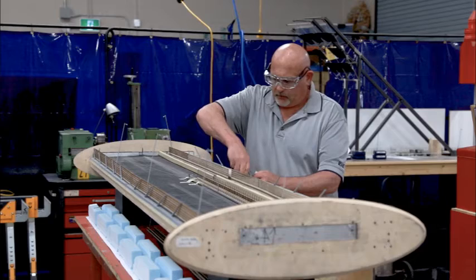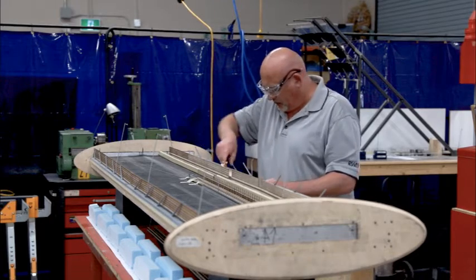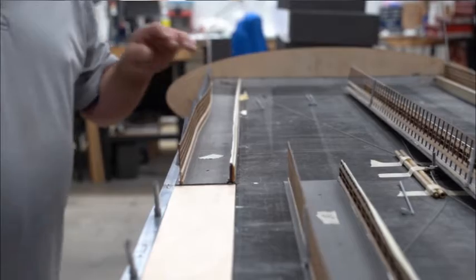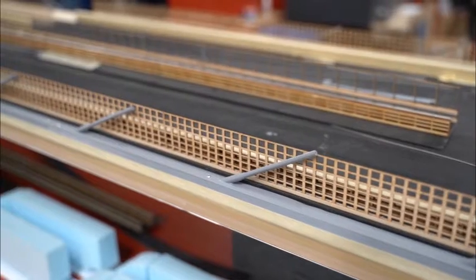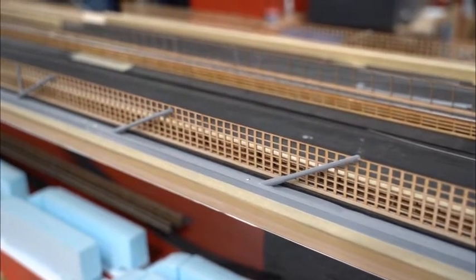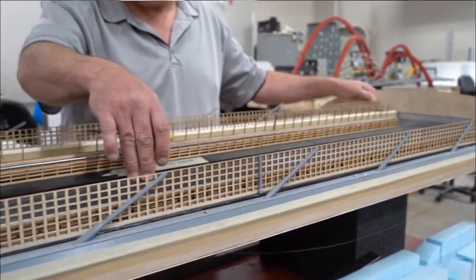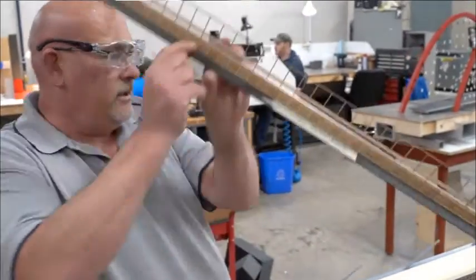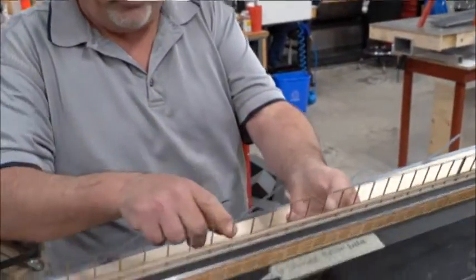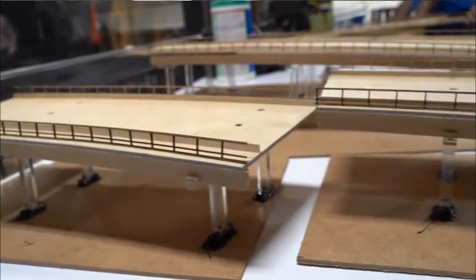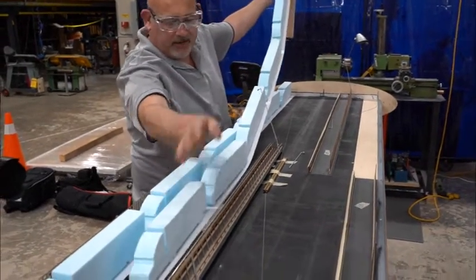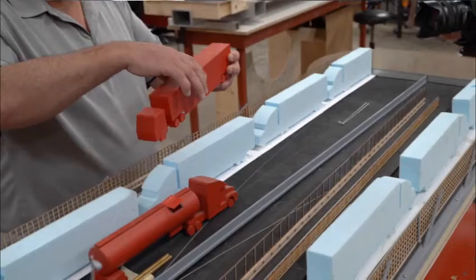The first round of testing we do is with the sectional model, where we model a short section, usually about 15 to 20 cable lengths of the center of the bridge, just so we can go through all of the different stability tests for a bridge, where we test it with every possible configuration that could go on with the bridge. We test the bridges with icing conditions, different variations of railings, different barriers, and different angles of attack just to check the stability of the bridge.